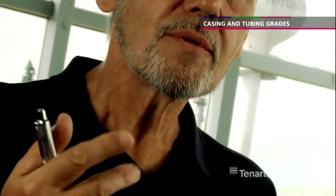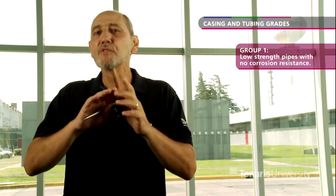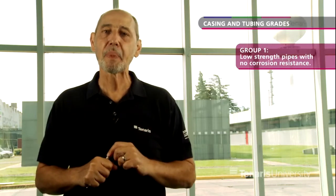Then we have casing and tubing grades. The different grades are classified in 4 main groups: 1, 2, 3, and 4. And within each group, different specified yield strengths are associated too. The main characteristics for each group are: Group 1 covers the low-strength pipes and has no corrosion resistance.